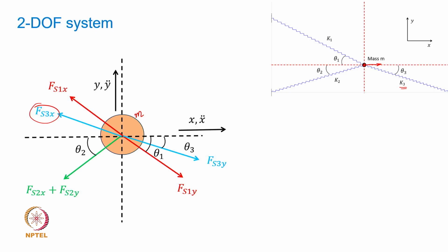The spring S3 is going to generate a force Fs3x, and that restoring force is going to be equal to K3 cos theta 3 into x.